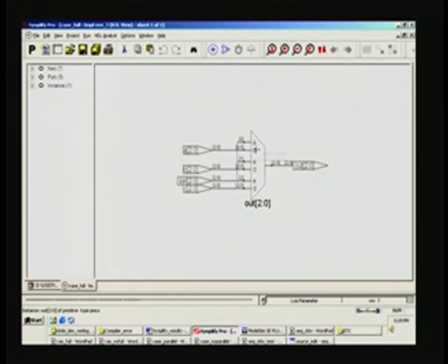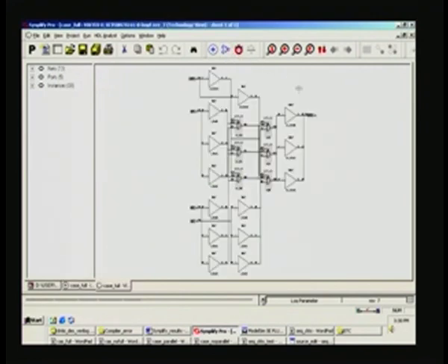As I mentioned before, D stands for data and E for enable, and what you have here is A, B and C through 0 bit. So, that is 3 bits each, and there is a select which is also 3 bits. So, in fact this select is distributed all through as 0 bit here, then 1 bit here, 2 bit here. In fact, they are all inside basically 2 input muxes, which we can see by technology view. So, this is what it is.